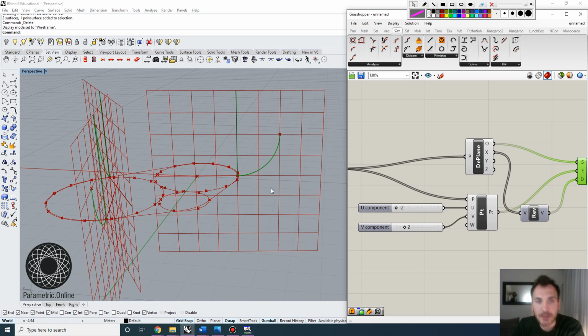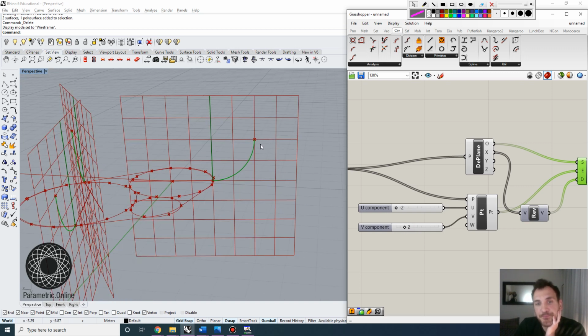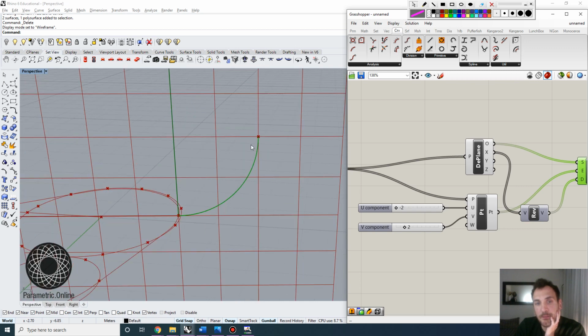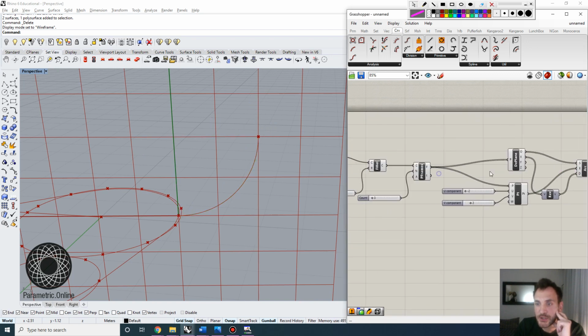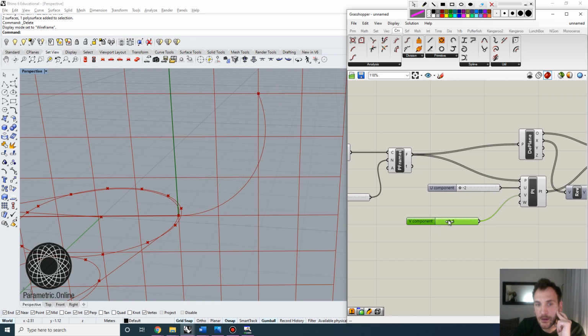And you can also make sure that these arches are somewhat like parts of a circle, right? This is not something I have built in the initial script, but basically you can make sure that the x and y coordinates of this point are identical, so that it will define almost like a radius. If these are r, then this point will be resting on a circle, right? So you can maintain this by just building a relationship with these 2 parameters.